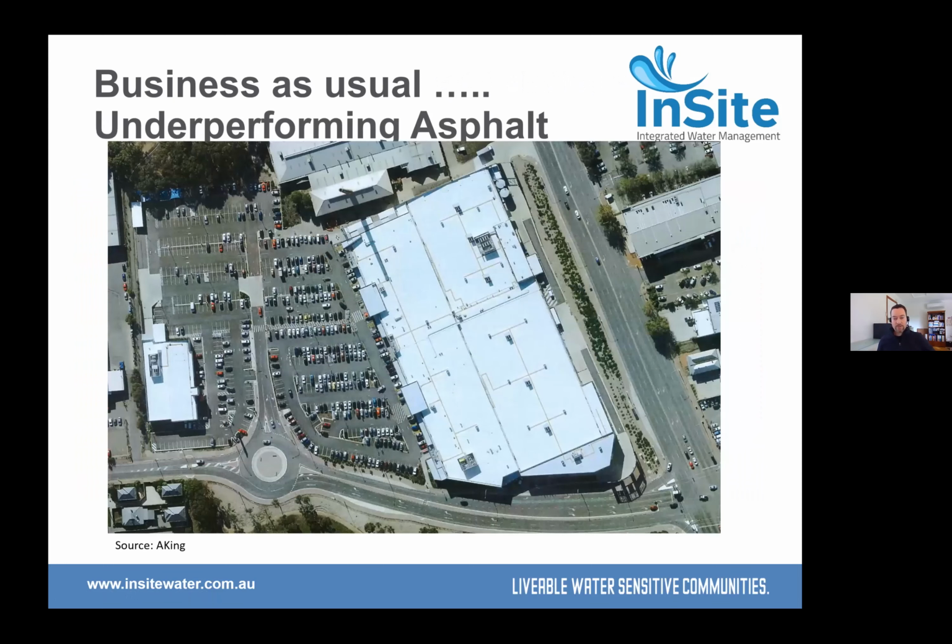It's very difficult to replace underground drains, and redevelopment of this sort creates a big burden on existing infrastructure. The same goes for commercial and industrial development that just completely makes the site impervious. Now, there are a lot of ways to be doing this development that takes responsibility for the stormwater and reduces the impacts of development, both in the volume and the flow rates, and also the water quality of the stormwater that comes off the site.